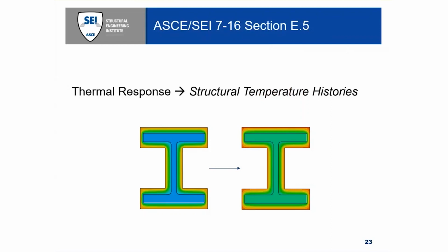The structural design fire is a subset of design fires because they're always uncontrolled. But once you determine the structural design fire, Section E.5 provides requirements for evaluating the thermal response of the structure using heat transfer calculations. And once that thermal response is determined, it can be evaluated as structural temperature histories, so the temperature of a given component at a given time.